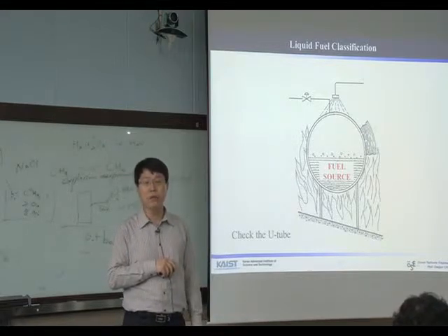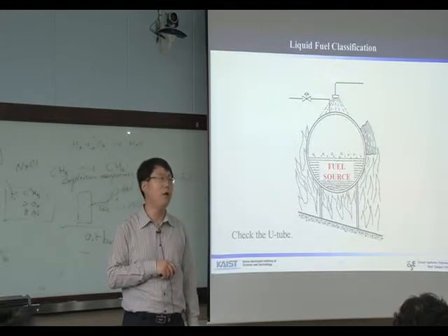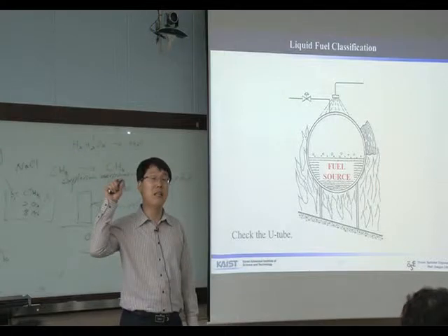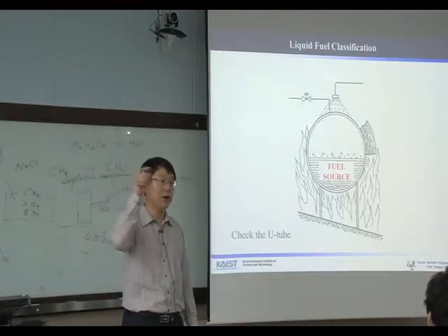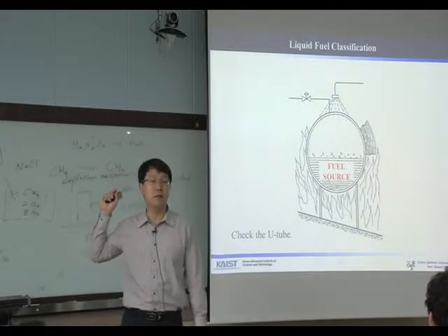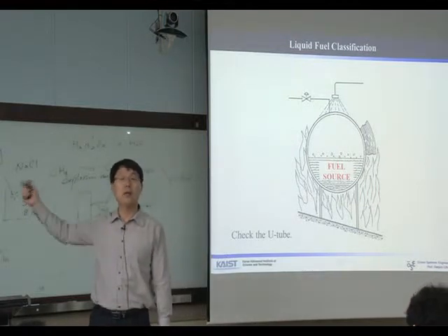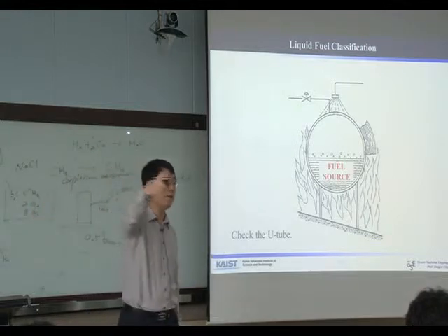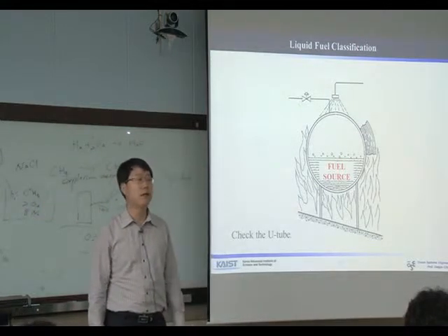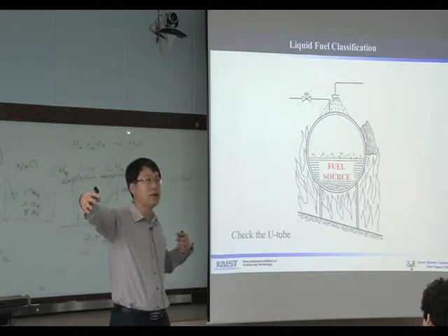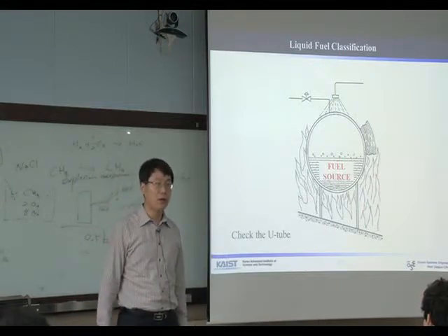Anyway, we have fire. The fire in offshore is very strong. Considering the speed of the leak, we have a jet fire. The leak just after the hole, the leak point, is soaring. So the speed of the jet is tens of meters per second, and the length is tens of meters.